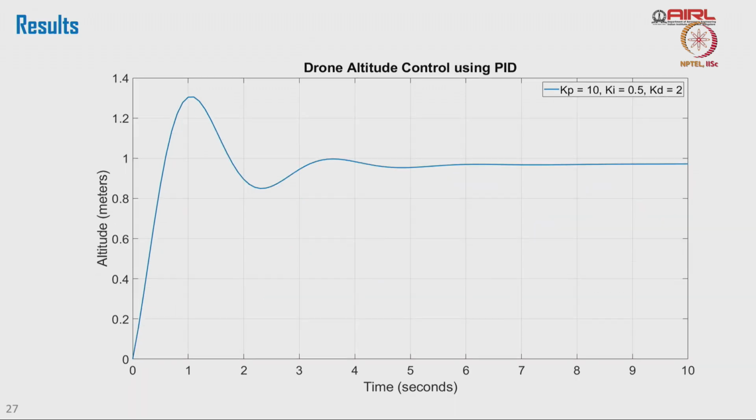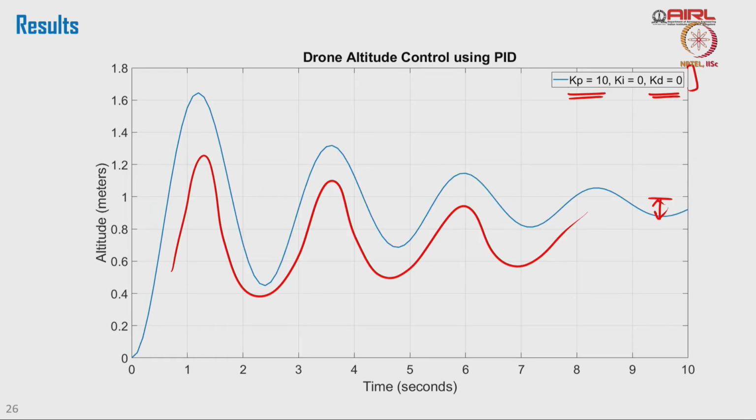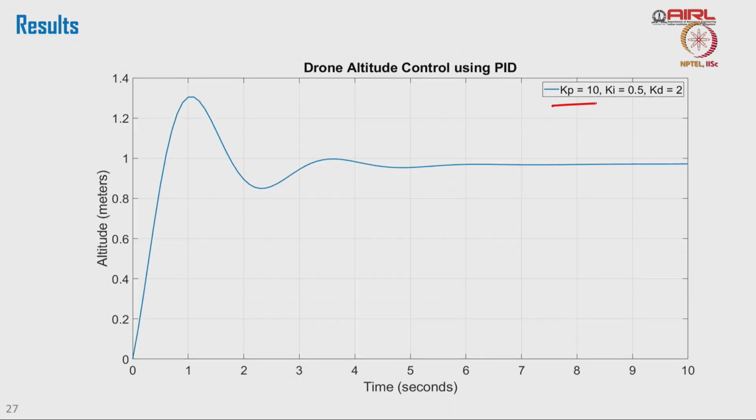Okay, fine. Now, what we do here is that in the second example, Kp remains unchanged, Kd is increased from 0 to 2. By doing that, we see that the derivative counterpart actually imposes damping into the system. That is why now the oscillation is reduced. Compared to what it was before, having a derivative term has reduced the oscillation. So, we can conclude that it is going towards stability.